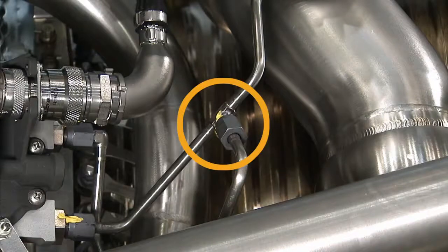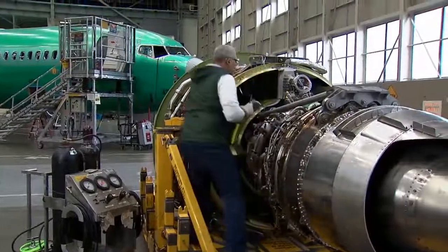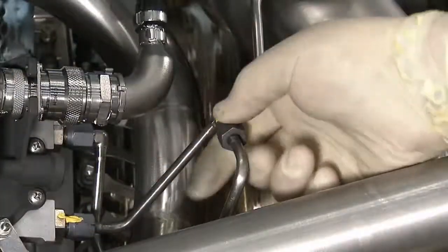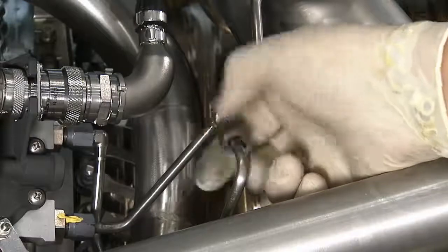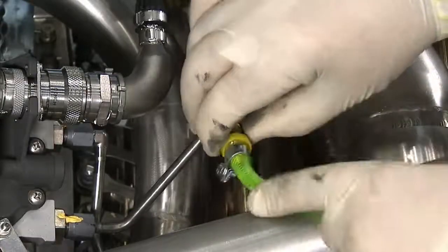On the left side of the engine, this T fitting takes air from the low stage duct and sends it to the bar and PCCV. To simulate the supply air to the bar and PCCV for testing, remove the supply line from the anti-icing duct to this T. Note that to save time in this video, all fittings have been loosened ahead of time. Then attach the supply hose from the test supply assembly at the T.